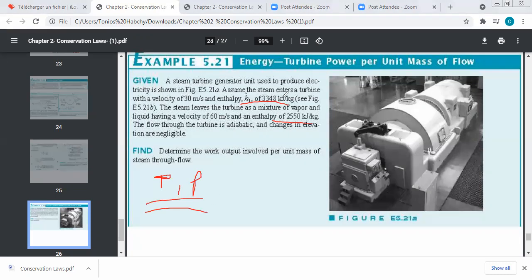If it's water, you have to know the temperature and the pressure, and then you go to your thermodynamic tables, you select the entry corresponding to these two conditions, and in the tables for this temperature and this pressure I have the following property for my fluid.